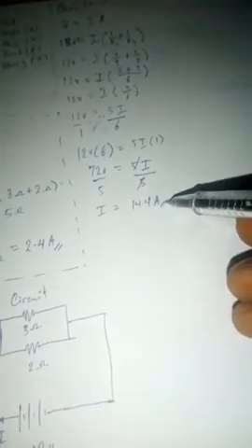Now we're going to be cross multiplying. Naturally 12 volts is already divided by 1. By cross multiplying, we multiply 5 by 1 and 12 volts times 6. That's 12 volts times 6 equals 5 multiplied by current times 1. So we're going to have 6 times 12, we'll have 72 volts equals 5 multiplied by current. Dividing both sides by the coefficient of the unknown, which is 5, we have the current equals 14.4 amps.